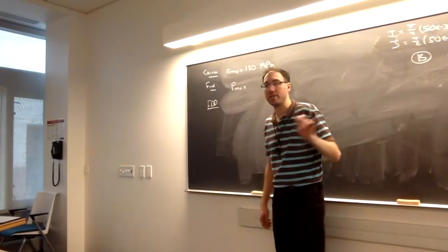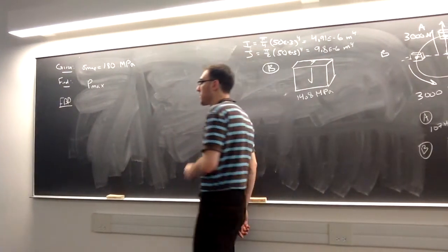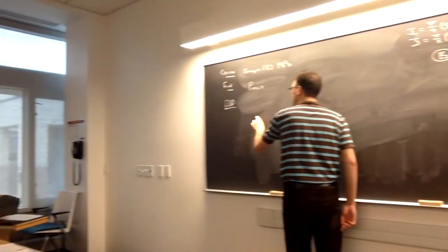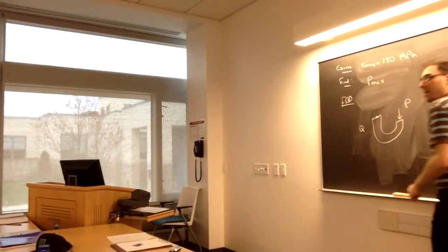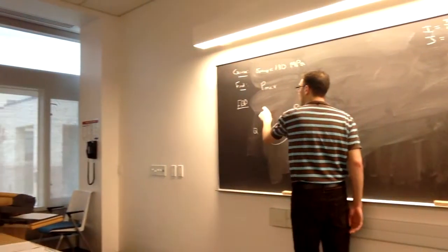They're telling us to cut across that plane AA, and we're going to see pretty quickly here we're going to have a problem. This is actually a 2D problem, not a 3D problem, so in that case it's a little bit easier. But if I'm cutting across AA there, and at that cut surface, because I'm only in 2 dimensions, I'm going to have 3 internal forces.